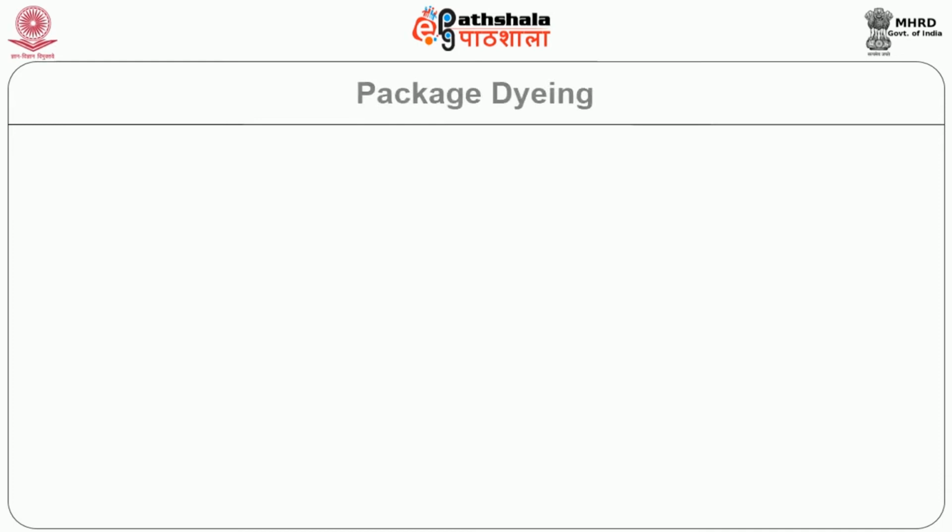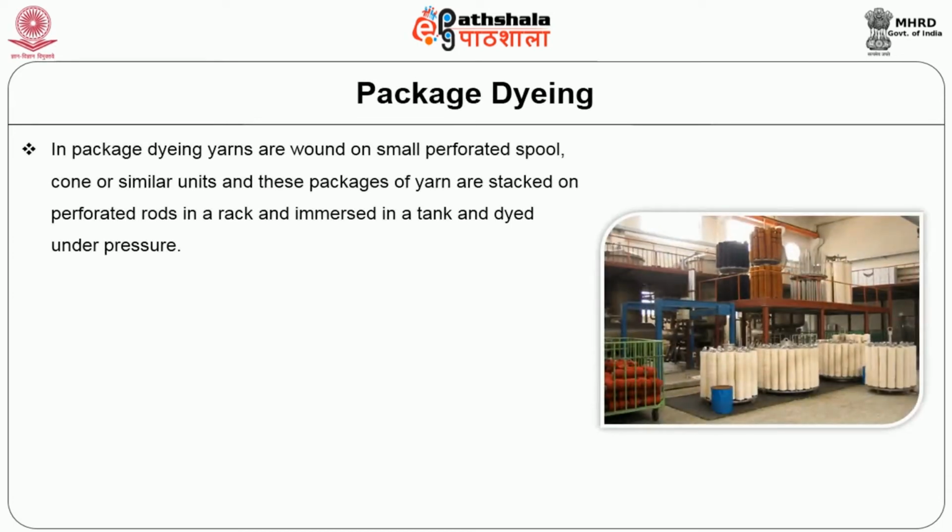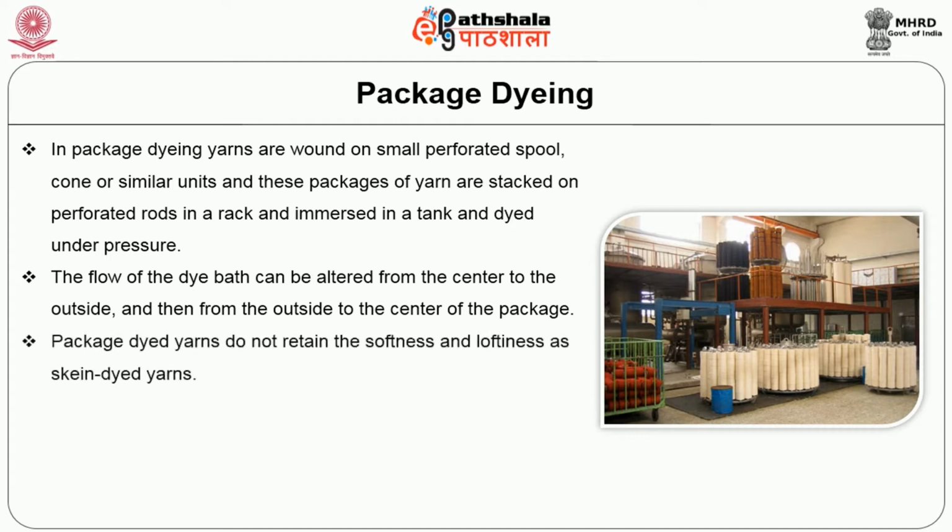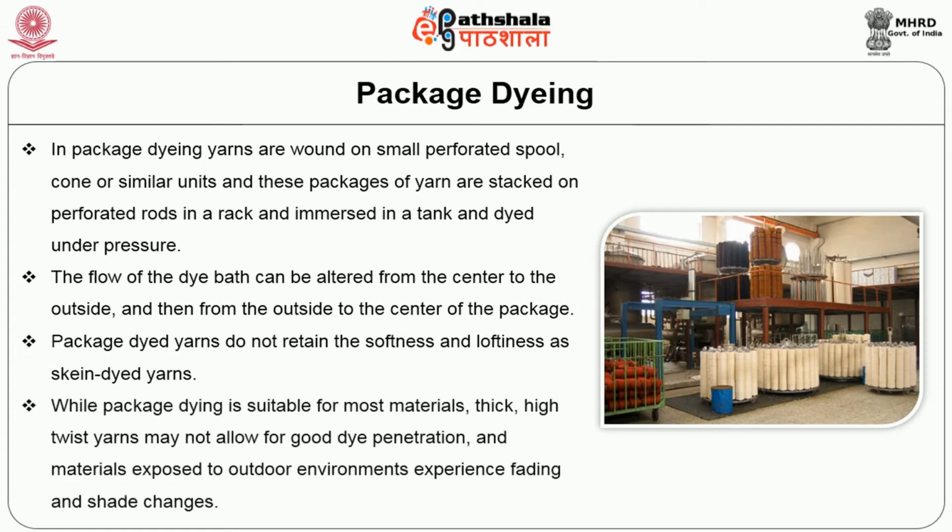Package dyeing: in package dyeing, yarns are wound on small perforated spools, cones or similar units, and these packages of yarn are stacked on perforated rods in a rack, immersed in a tank and dyed under pressure. The flow of the dye bath can be altered from the center to the outside and then from the outside to the center of the package. Package dyed yarns do not retain the softness and loftiness of skein dyed yarns. While package dyeing is suitable for most materials, thick, high twist yarns may not allow for good dye penetration, and materials exposed to outdoor environments experience fading and shade changes.